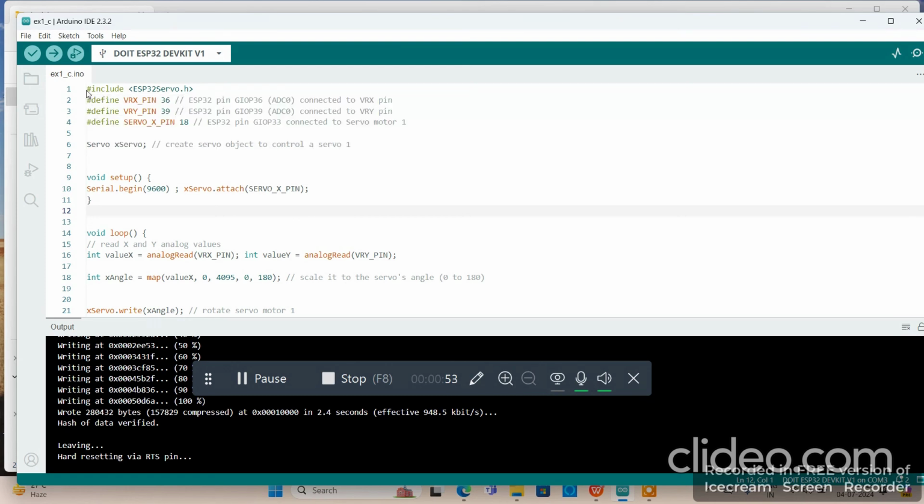Here we are using one library, the ESP32 Servo library, and with the help of that library we are interfacing the analog pins corresponding to movements from the joystick to pin number 36 and 39. Actually, if you see the ESP32, 36 and 39 are not mentioned. They are mentioned as VP or VN on the ESP controller. So connect there. Anyhow, in the video I will show.